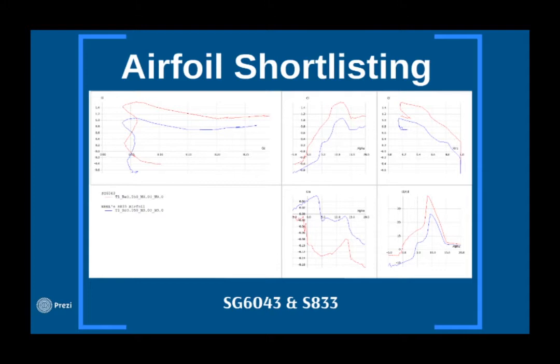However, near the nose cone, the blade experiences high forces as it supports the rest of the blade and its moments, and thus requires a thicker airfoil to ensure that the blade is structurally sound. In this aspect, S833 fulfills this criteria while still having good aerodynamic properties, albeit providing lower lift than SG6043. To ensure structural integrity without compromising lift to a large extent, airfoil S833 was used from the root up to 60 mm of the blade, while airfoil SG6043 made up the rest of the blade.